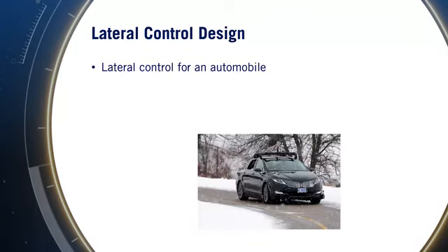One of the main concerns in autonomous vehicles is ensuring the vehicle can precisely follow a predefined path, executing the motion plan devised in the higher level planning module. This is the main goal of lateral control, which must select the steering angle required to correct any errors that accumulate, and track changes in the path direction as they appear.